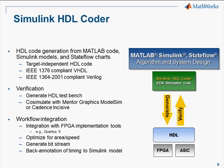Simulink HDL Coder supports HDL code generation from MATLAB code, Simulink models, and Stateflow charts. The HDL code that it's generating is target independent. So you can go to different types of FPGAs, you can go to ASICs, all off of that common HDL code. It's either in VHDL form or Verilog, of course. And then for verification, we support the ability to do verification using a standalone HDL test bench in your HDL simulator of choice. MathWorks also offers co-simulation interfaces between MATLAB and Simulink and either Mentor Graphics ModelSim or Cadence Incisive.